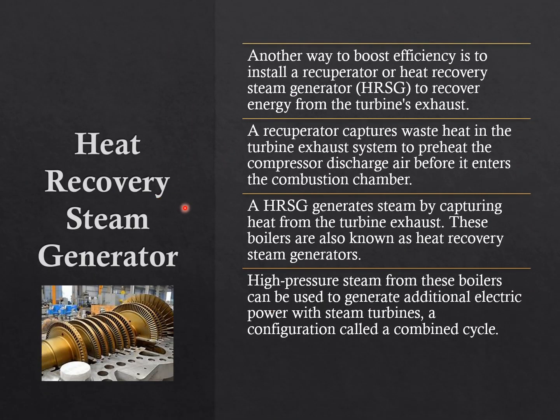The heat recovery system generator is just another way to boost the efficiency. We install something called a recuperator, which is used to recover the waste heat coming out of the turbine exhaust. You capture that heat and use it to preheat the compressor air. That's what we do.